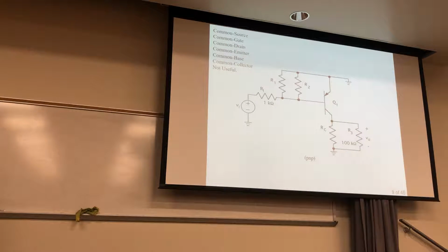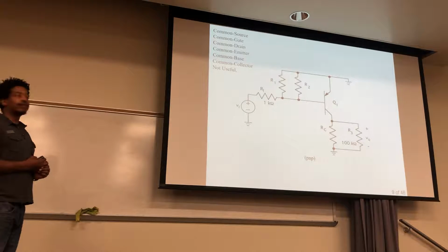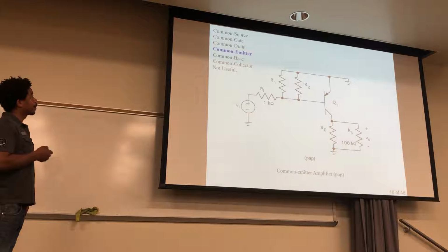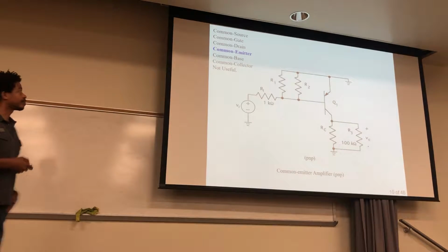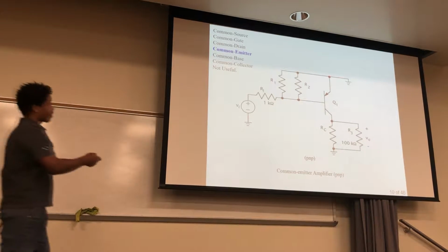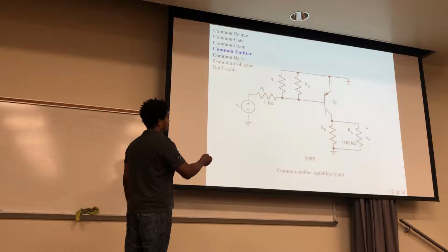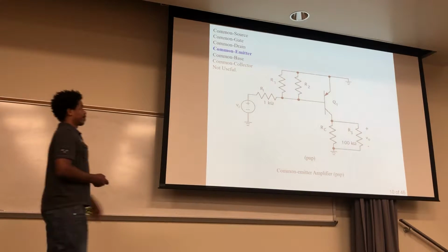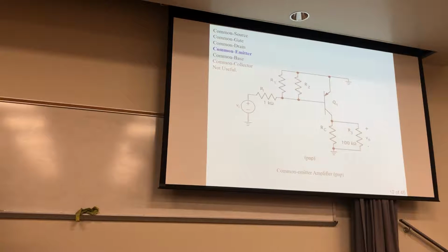Now, which is it? Common emitter? Yes, common emitter. See that? So even though the ground is up here, it's all in reference to the input and output. So same thing. All these 3 points are connected.